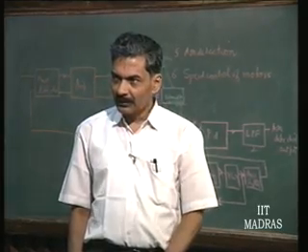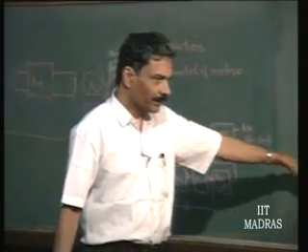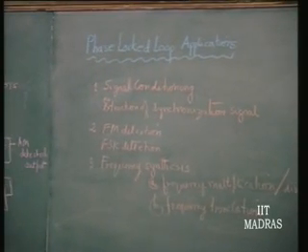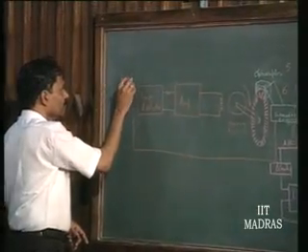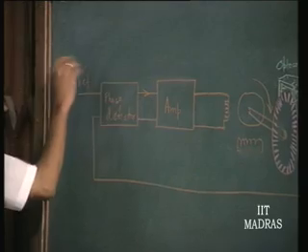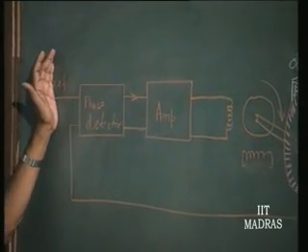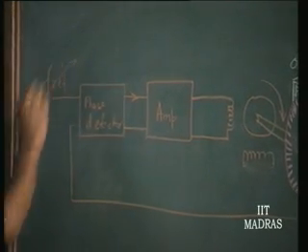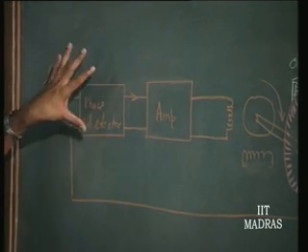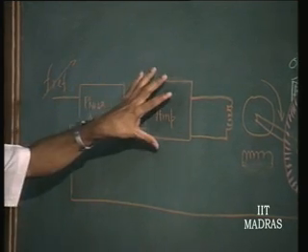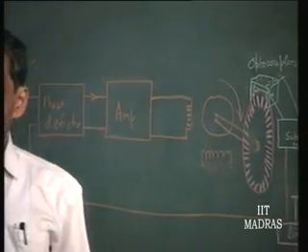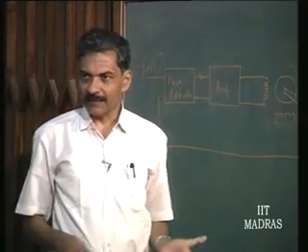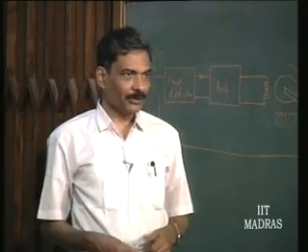So, we can therefore, using frequency synthesis technique, obtain from a reference any frequency input. So, this is the reference frequency coming through a frequency synthesized scheme, and that can be adjusted. This is applied to the phase detector, amplifier. Now, the low pass filter is nothing but the winding of the motor itself, the control winding of the motor itself acts as a low pass filter. You do not have to specially put any low pass filter.